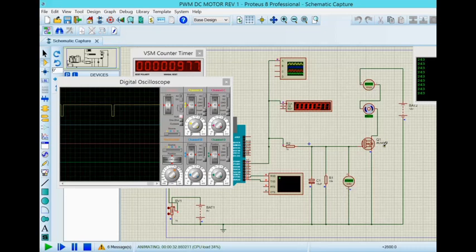For this MOSFET, the nice thing about it is that it can be fired within the Arduino voltage. So within the 5 volts, it's pretty much fired. It might get hot a little bit, because, I mean, 1 amp going through, maybe not. What I'm saying is, maybe not 1 amp, maybe 2 or 3 amps might get hot, because there's some resistance value when you fire it at this voltage. If you want that resistance value to be lower, you have to fire at a higher voltage. This guy typically requires like 10 volts, but 5 volts gets the job done for the Arduino, and that's why I like it.